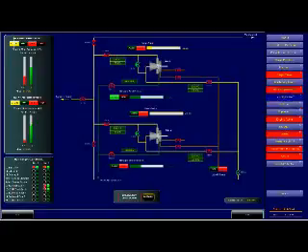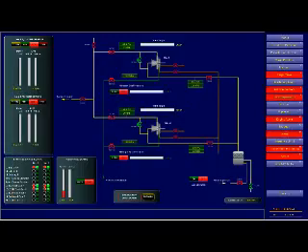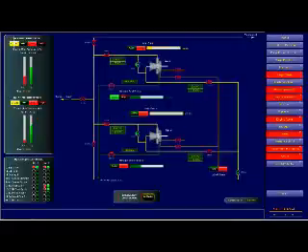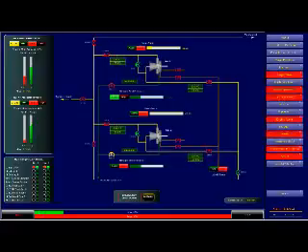Our low duty compressors, again, we keep all of them on standby, so if we need them anytime, then we can use them. And of course, the nitrogen seal at the moment is not opened, so we should have the nitrogen also coming to the pumps or compressors, just in case we may have to run them if the shore is not giving us the vapor.